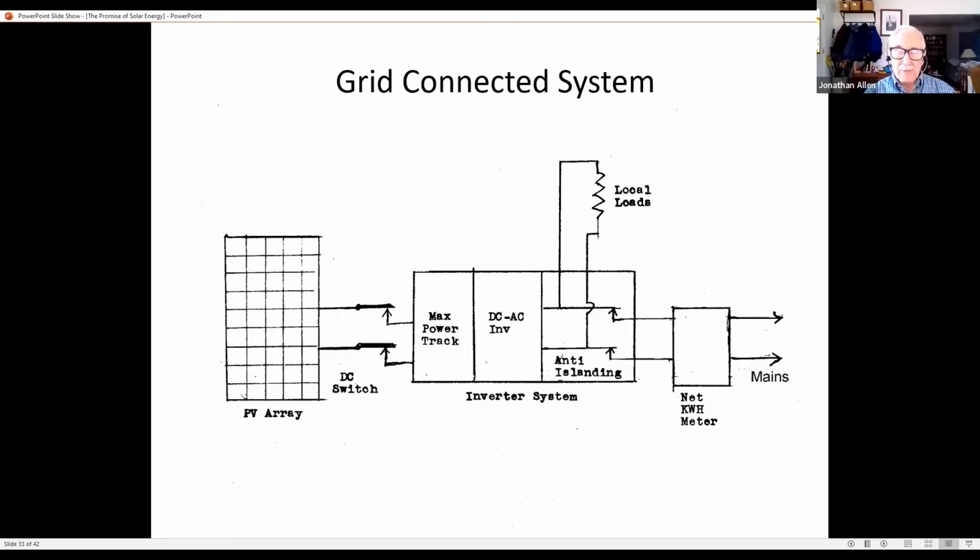So, for example, if a fellow is speeding in his gas hog SUV and smashes into a utility pole, pulling down the wires not too far from the house, the mains are broken, and the anti-islanding circuit will disconnect the inverter, so it will not stuff hazardous voltages back into the mains to endanger the poor guy who has to fix the damage.